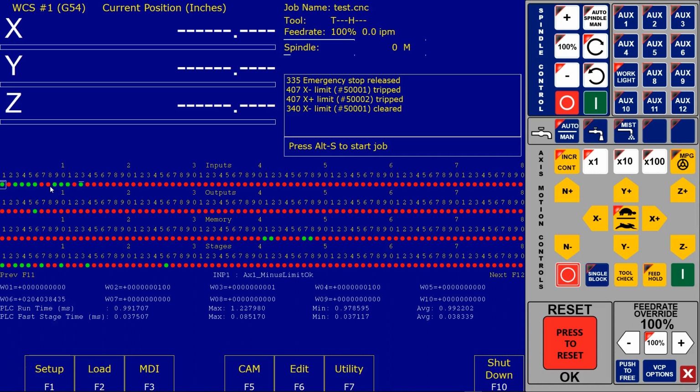That's perfectly fine. What they have to do, though, is leave inputs 1 through 6 as is, and then defeat them on the all-in-one DC, then wire their inputs to any of the other free inputs, and then in the motor configuration menu, just set that particular input to whatever input it was wired to. Okay, but long story short, on an all-in-one DC system, inputs 1 through 6 cannot and should not ever be inverted. Okay.